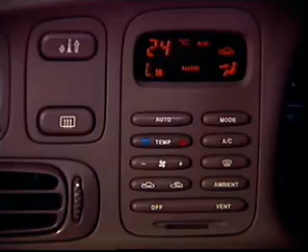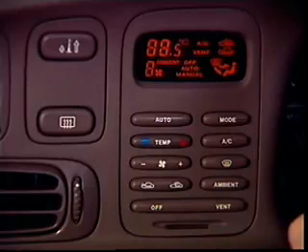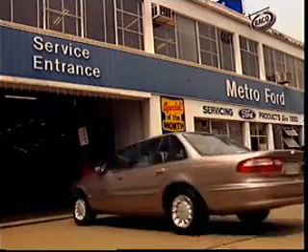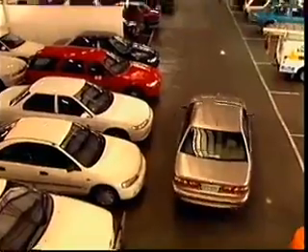Many electronic control units have a self-diagnostic function, which assists in locating faults that may be present in the electric system of the climate control system. Fault codes can be displayed on the vehicle's display screen. Each code represents a circuit and components whose signals are outside of the limits expected by the electronic control unit. The fault codes are stored in the electronic control unit's memory until they are cleared during servicing.